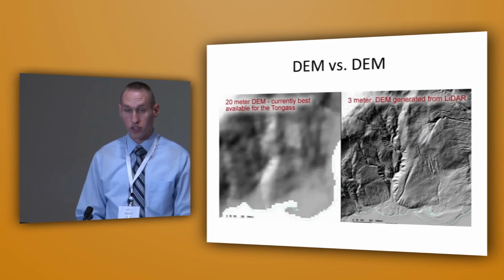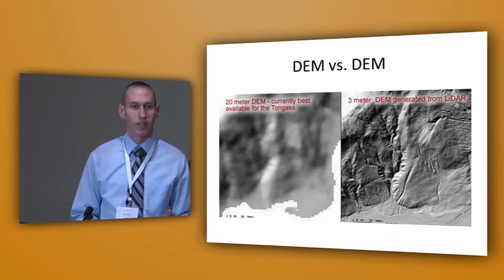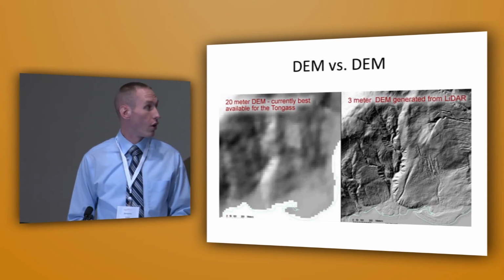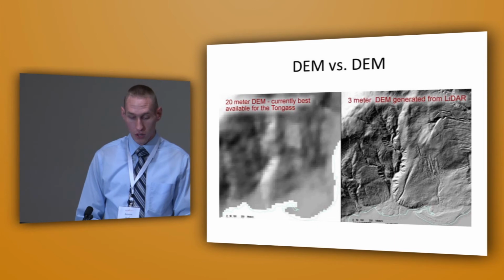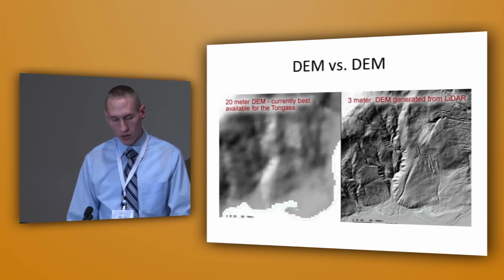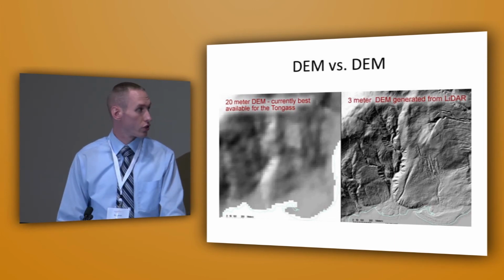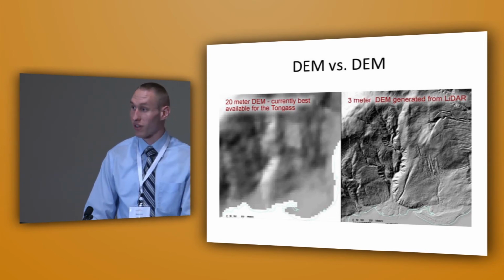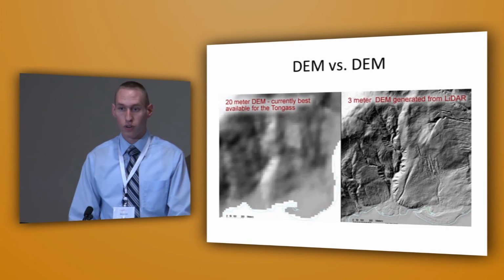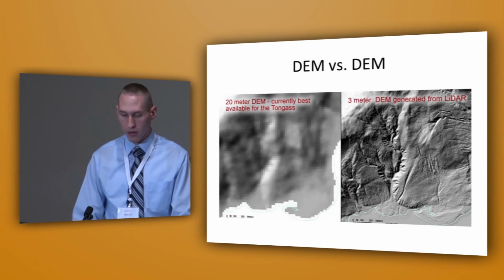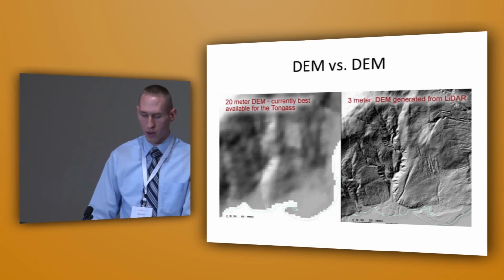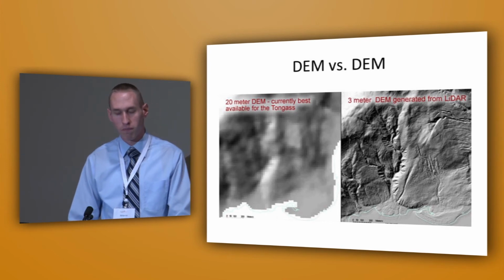As you can see here, this is not the data that I used. The data that I use is with the Geosciences division, and I don't really have access to it right now. However, this picture should suffice for what I'm trying to tell you. Basically, the DEMs that I downloaded weren't too much better than what you see in the picture on the left, and there's no way I'd be able to find traces of wells from the picture on the left. So what I decided to do from there was look at LiDAR data. And using raw LAS files and geoprocessing, I was able to make my DEMs look kind of like what you see on the right, maybe a little bit better.